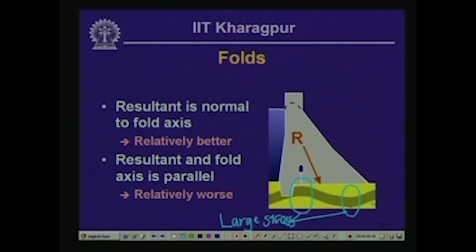So this is the fundamental reason why we want to orient a dam in a direction perpendicular to the axis of the fold.